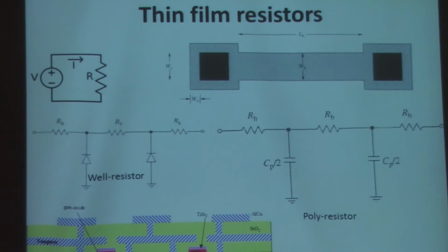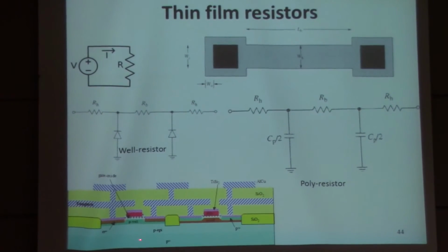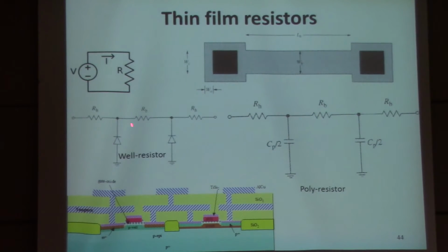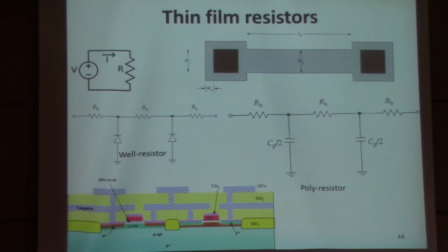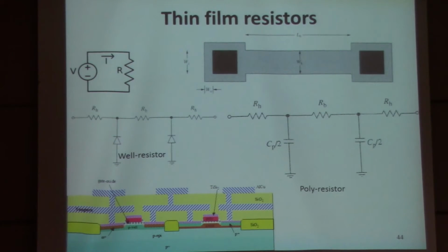Okay, now look at the transistors. You can use the polysilicon, or the active or doped silicon area, for well resistors or poly resistors. That's similar to the lower frequency operation, but for high frequency, the problem is this: you get a resistor, it's not a resistor.